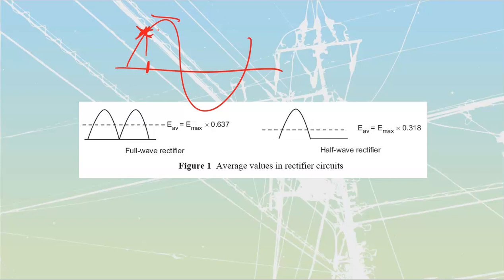And then we are going to have what is called our average value of voltage. We ignored that earlier this year because we said, hey, we're going to deal with it when we get to rectifiers. Well, the time of reckoning has come. We must deal with the average value of voltage. The average value of voltage is going to be a DC value of voltage. It is going to tell us what a DC meter would read. DC meters read voltage and current differently than AC meters, so we have to have different types of calculations to be able to find these things.